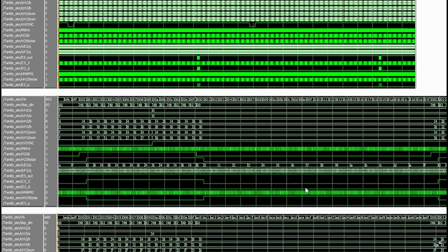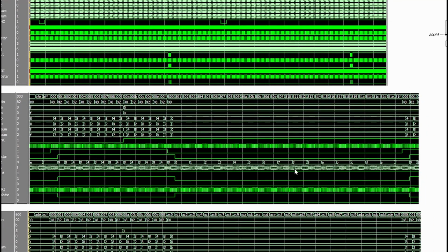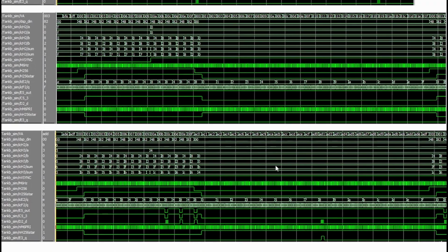With the zoomed in view, we can see how the counter works. So during the H blank period, the RAM is fed with values of the bullets. But you can see in this diagram, it's not enabled during this time because C53 is always high. And C53 was the chip enable. So it being high, it doesn't actually record any of this data. After that, the RAM is triggered to just count all the way through the RAM from 0 to FF. Now look what happens on the diagram below.